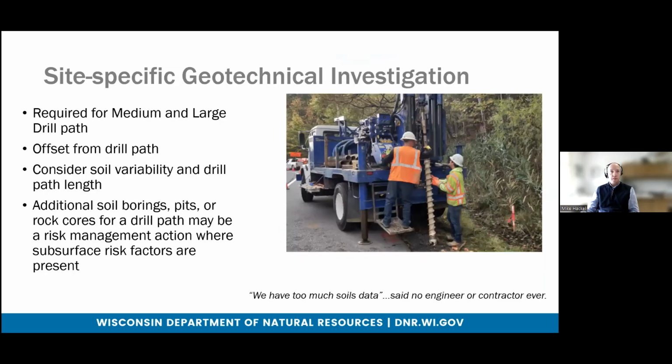And that, of course, is our next potential step: to complete a full site-specific geotechnical investigation with borings or test pits and a written report talking about what kind of soils we could encounter along the way. These are required for medium and large drill paths, when Jerry showed that chart earlier indicating the 3 various bore types that we've established in the standard. We'd want to make sure that we're doing this soil investigation slightly offset from the drill path so that our drill path is not intercepting these now weakened soil areas from the test pits or the borings.